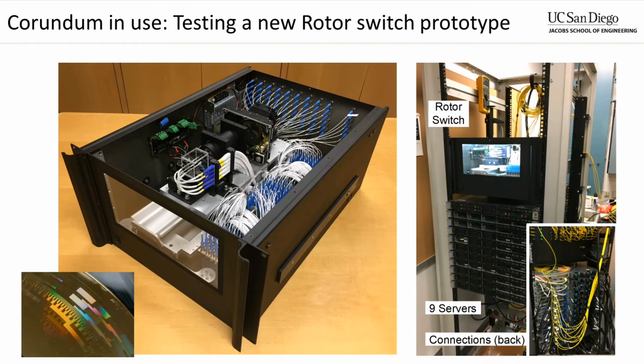There are 11 servers in the test setup. 9 contain Alpha Data FPGA boards that are populated with 40G QSFP+ PSM4 transceivers. The 4 channels of the transceivers are used independently, providing each of the 9 hosts with 3 connections to the optical switch. In this case, we are using the switch to emulate 3 separate switches with offset schedules such that only one switch can reconfigure at any given time.